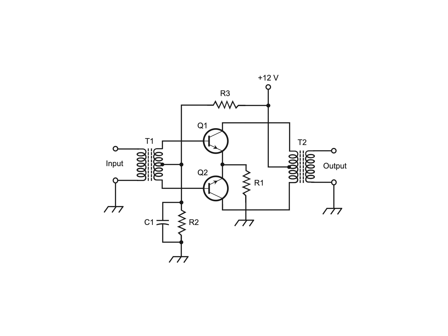If the original input signal contains little or no power, then this circuit won't get enough drive, input power, to produce any output signal. In order to work properly, a power amplifier needs a signal that has a modest amount of power to begin with, otherwise it will simply suck up the feeble input signal and produce nothing from it other than a tiny amount of heat in the components. The previous circuit, the audio preamplifier, provides enough output power to adequately drive a push-pull audio amplifier. The crystal radio circuit doesn't.